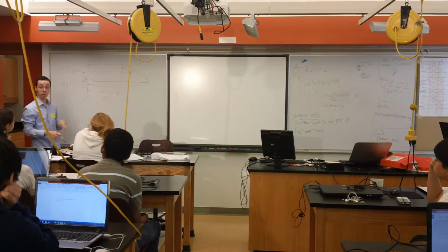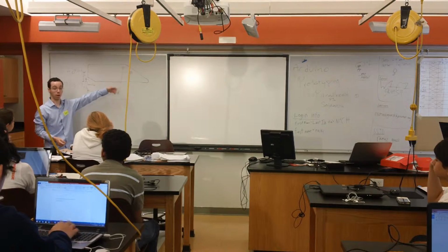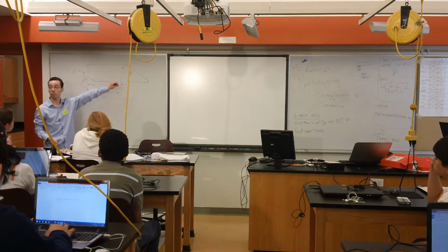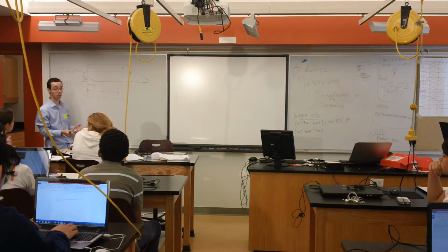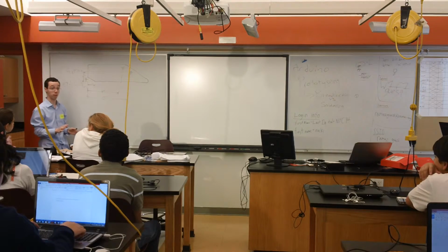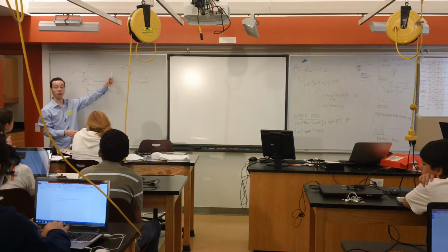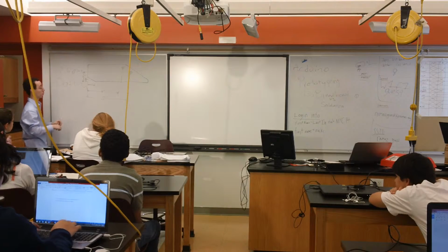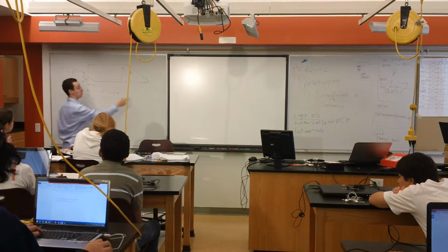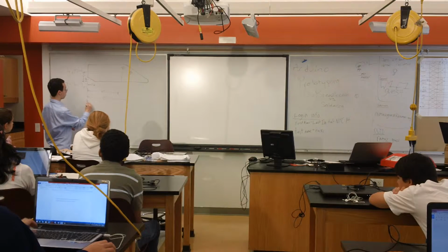Okay. That's how we specify position, but now I know there are holes here. I don't know what size they are, I don't know if they go through the part, I don't know if they've got countersinking on them, I don't know if they've got screw taps. I'm not going to talk about a lot of that, because for most of you, the only relevant thing is going to be where is a hole and how big is it. So I'm just going to specify that. So now we know where our holes are. We want to know what size they are. We want to know what size this is. Well, let me just finish up the where real quick on both of these things.